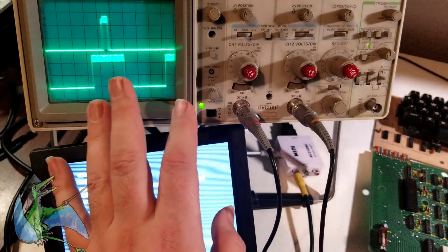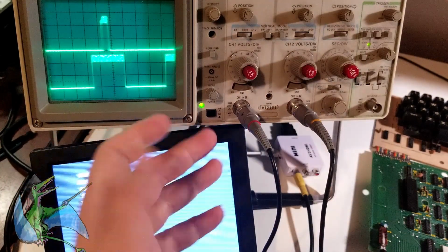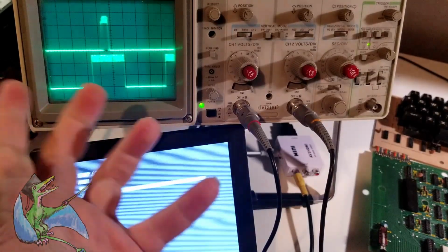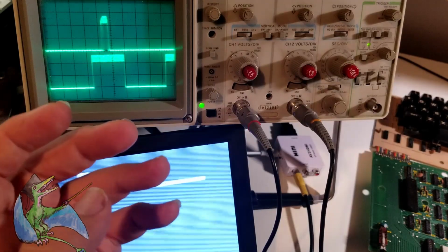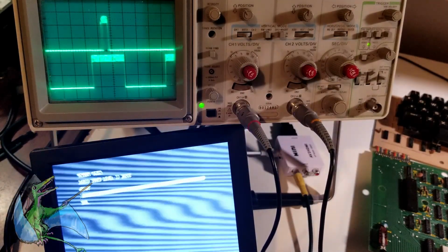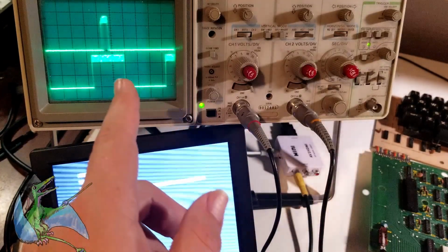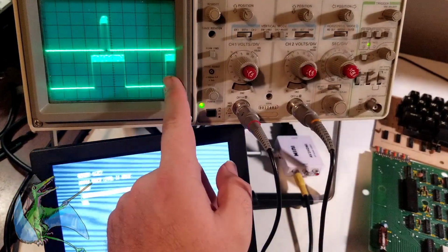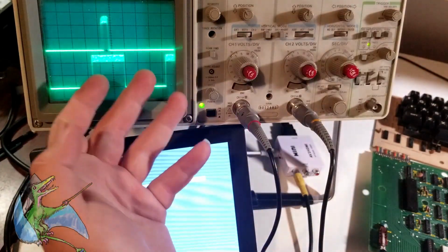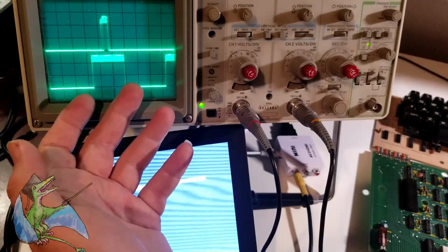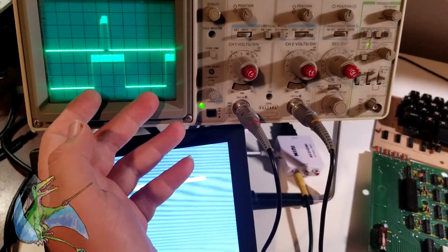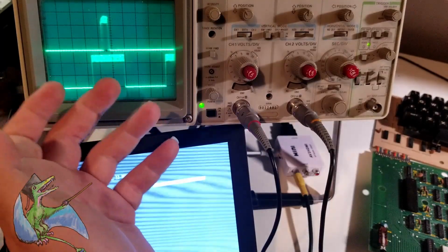So, this is an old-fashioned scope. There's nothing digital about it, but scopes still have some intelligence, even these old analog ones. They have a feature called triggering. Triggering is when the sweep across the display is derived from some action the scope detects, like when this value goes up or goes down.